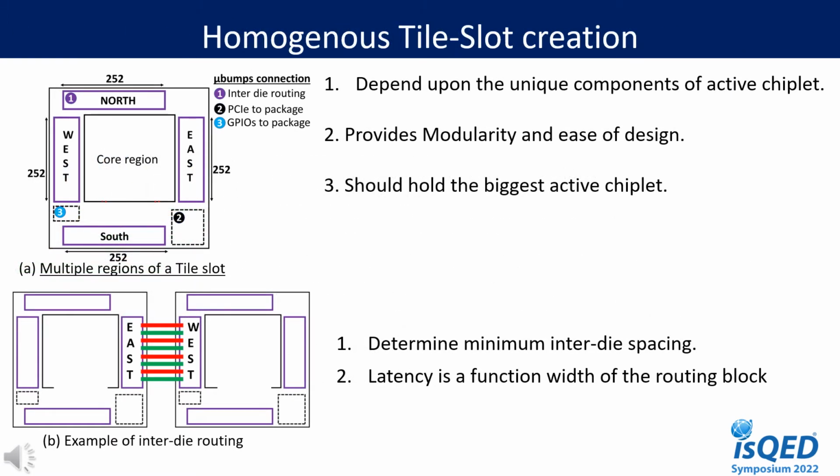Since the tile slots are designed on a passive base interposer, we do not support any active components. We support only metal routings. That needs to be decided based on the latency between the dies or number of metal layers required based on the number of IOs and so on, process considerations. However, that also needs to support micro bump connectivity on the one side and TSV all the way to C4 connectivity on a double bond process.